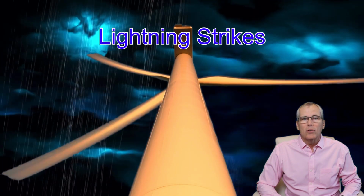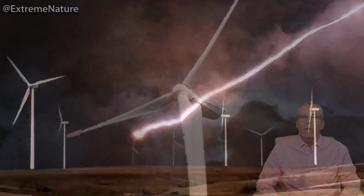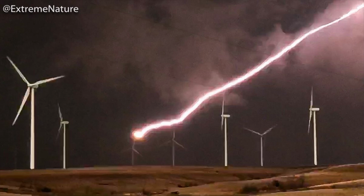Wind turbine blades are vulnerable to lightning strikes, which can cause significant damage and downtime for the turbine. To protect the blades from lightning strikes, wind turbine operators often implement lightning protection systems. These systems typically include a combination of air terminals, conductors, and grounding systems that help to dissipate the electrical charge from a lightning strike and redirect it into the ground.